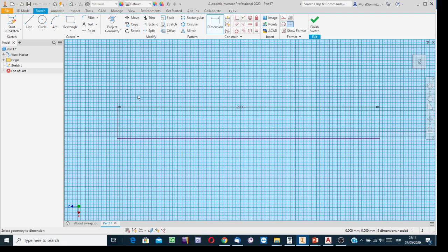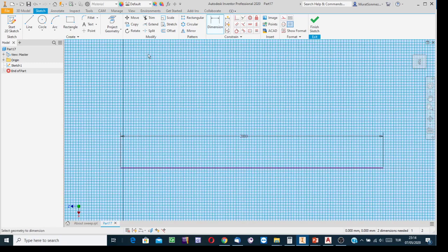And then, if you have Excel data, transfer the data to Inventor to have the curve. If there is no such data, then mark the points, locate them with respect to each other, and then join the points with a continuous line. Say that this is the first point, this is the second point, etc.